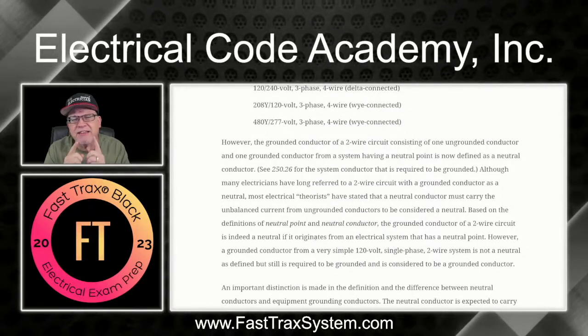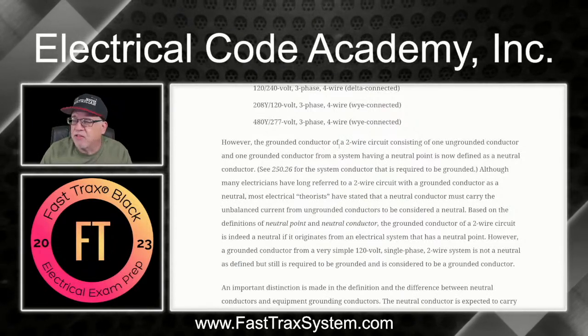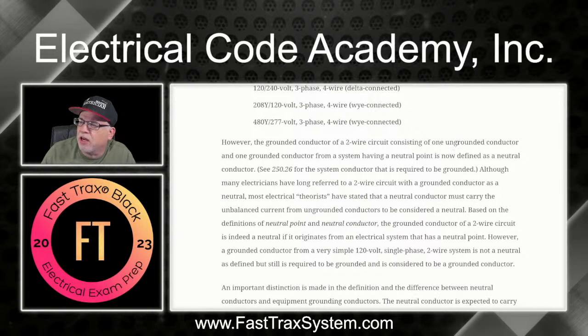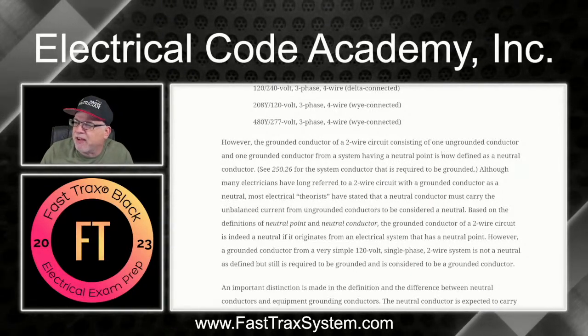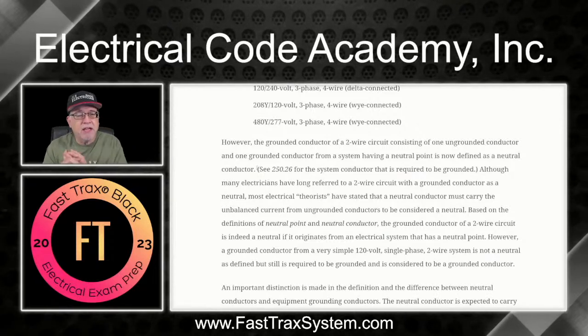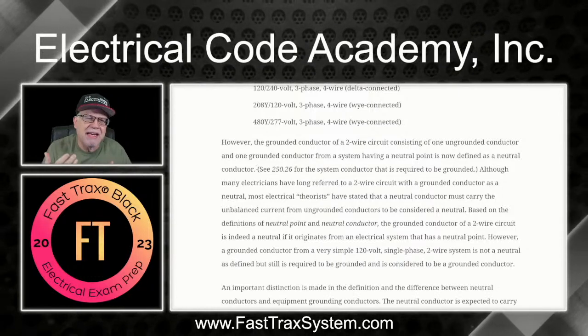All right, so let's look at this discussion. It says, however, the grounded conductor, which it is, in a two-wire circuit consists of one ungrounded conductor, that's the hot, and one grounded conductor from the system having a neutral point, is now defined as a neutral conductor because it has a neutral point where it's connected. So the theorists still will say, yeah, but it's not carrying the maximum unbalanced load between phases. It can't be a neutral.